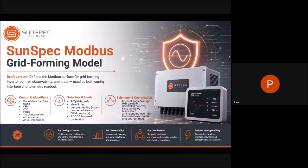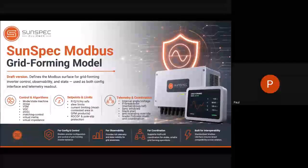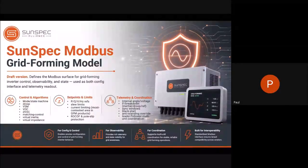Okay, so this is more than just grid down. Now the inverter is not just following the grid. The inverter is acting like a primary source on the grid. Yes. On the grid. Okay. Yeah, so that's a big leap. When somebody said it was just for when the grid is down, I thought, well, okay, we already do that. But yeah, I see now. So basically this is saying, how can we use the inverter to emulate a rotating generator?